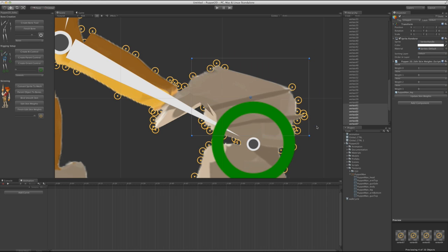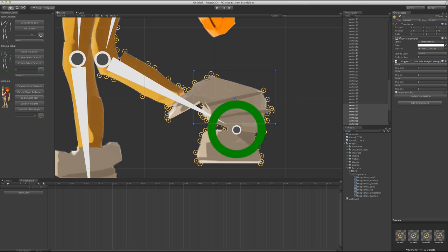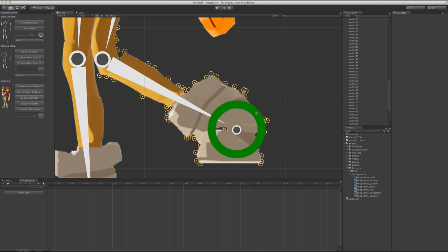Just select those ones, and over here in the inspector, we basically have which joints it's weighted to. So you can choose which joint, and you've got the weight for it. For example here, we probably want to have it all weighted directly to the knee. So we're going to switch that to the knee, and if you're updating multiple vertices at once, you can just click this update skin weights, and then everything selected will be updated.